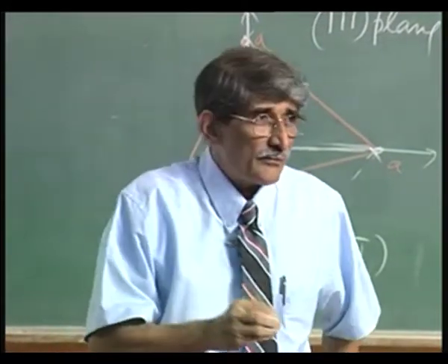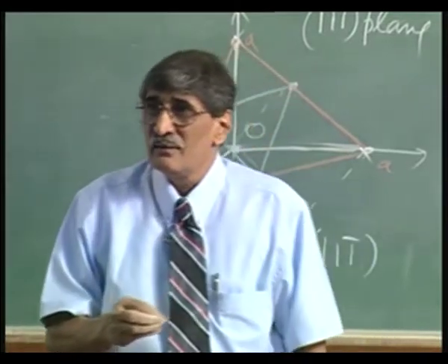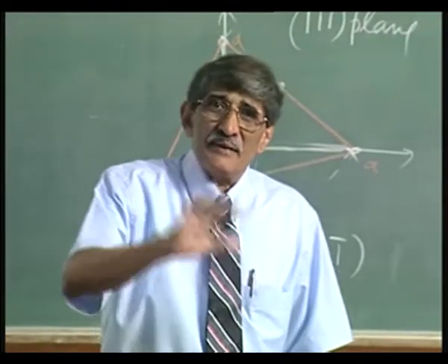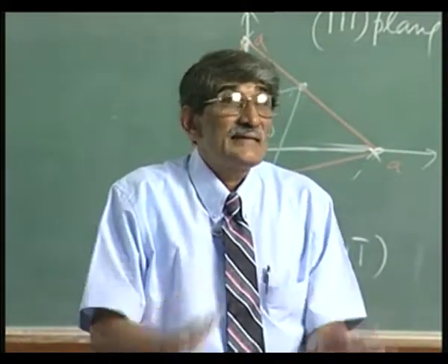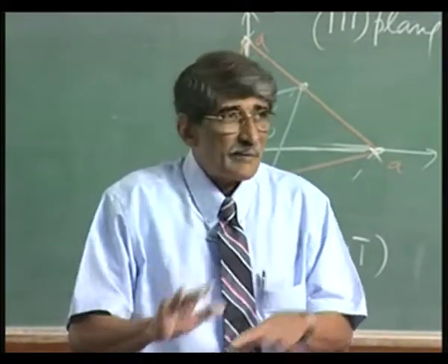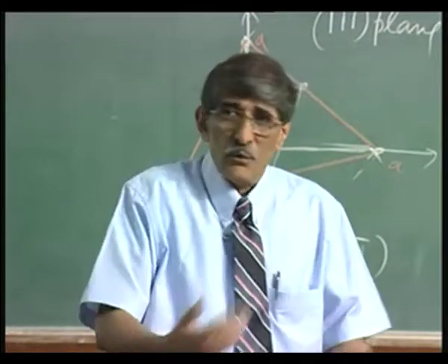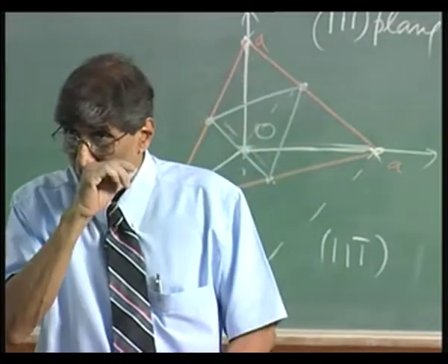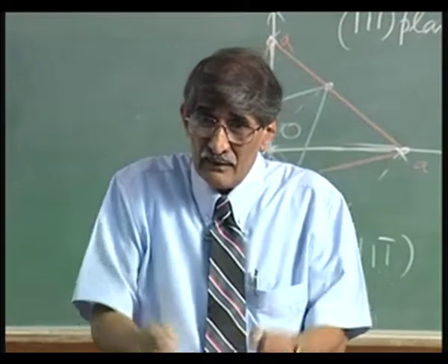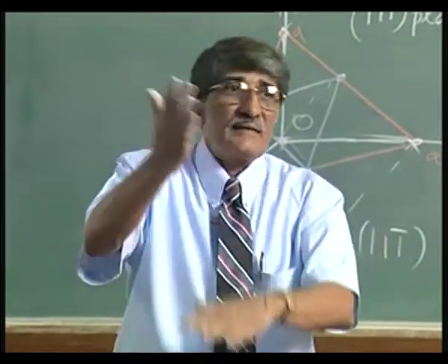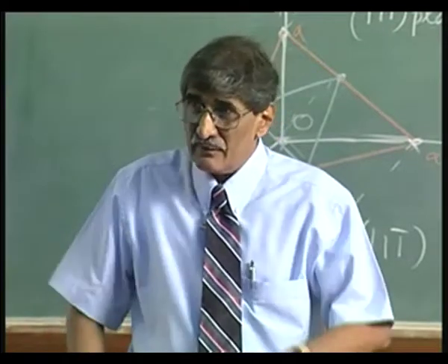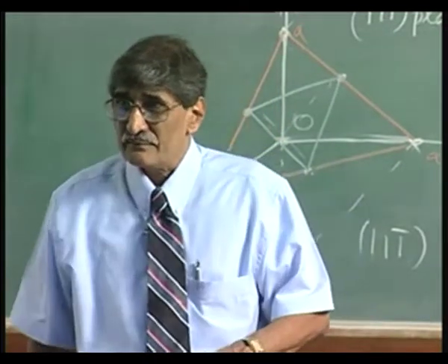It is only covalent bond, okay? And it is the 111 plane, because along the 111 plane binding is good, because that is densely packed. Number of atoms along the 111 plane is more, that is densely packed. So that is why, when you cleave the 111 plane, it does not break across it, it comes off parallel to that, because that plane is bound together.